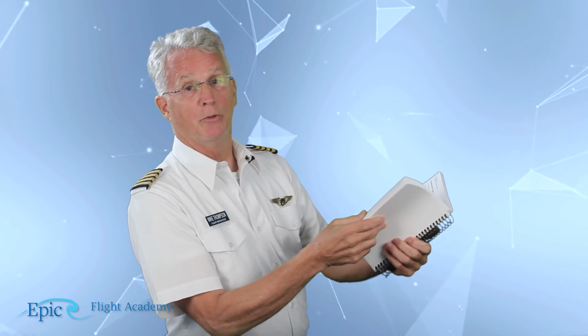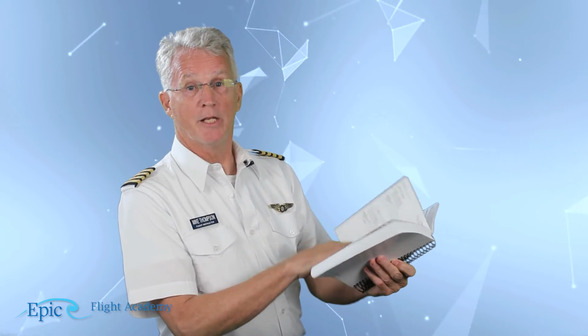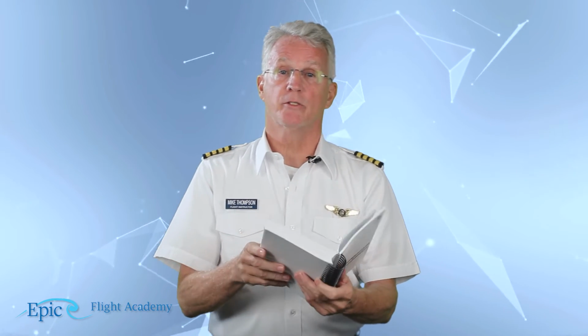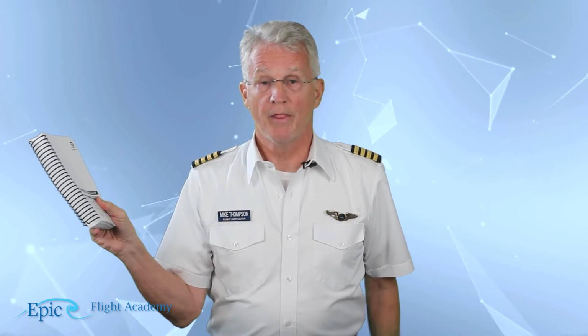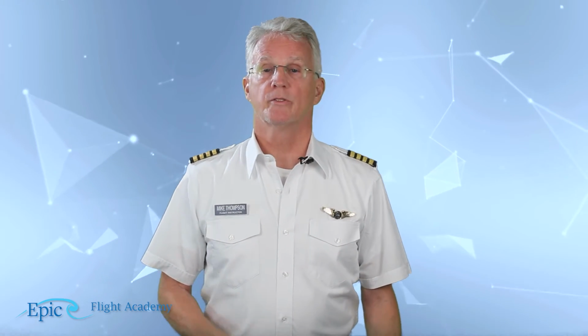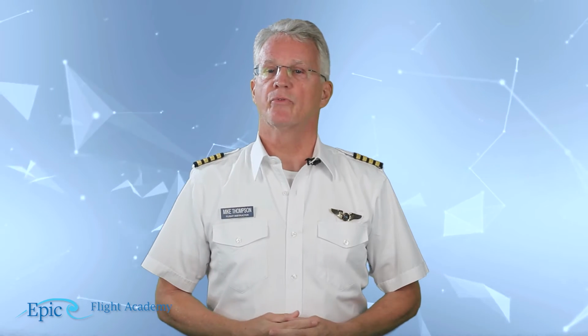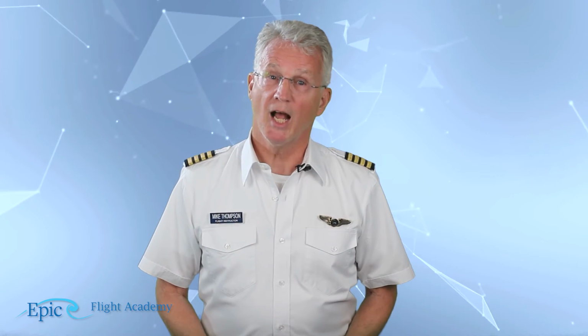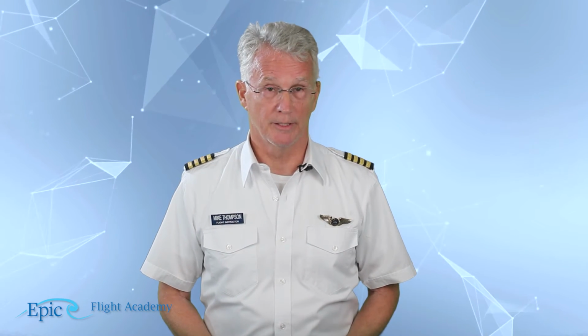You'll find that here in section 2 on limitations in the airspeed limitations table. The maximum window open speed is the same as VNE. So if it was me in an actual situation, I think I'd open the cabin windows to help ventilate.